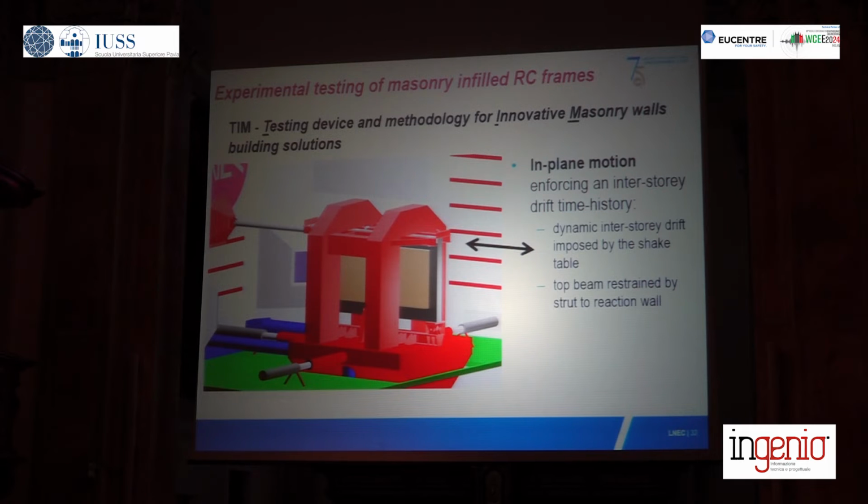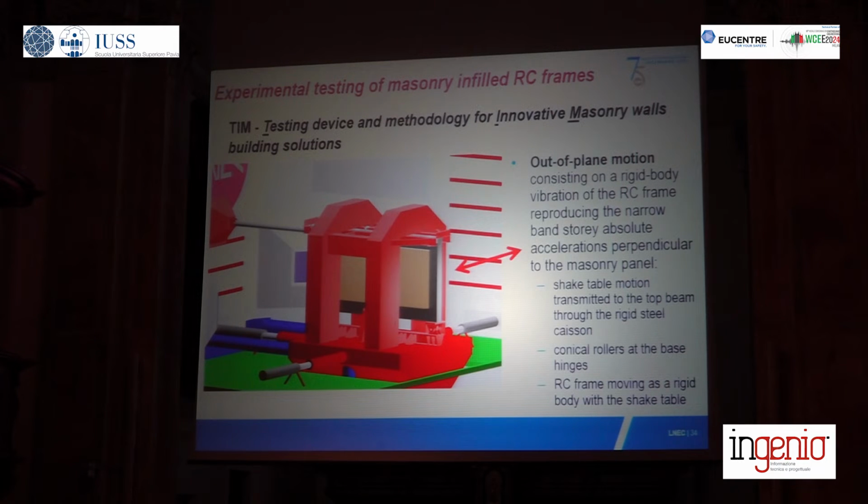Okay, so we impose the in-plane drift by having a fixed strut to the reaction wall and the motion of the shake table in the in-plane direction, and then we impose the out-of-plane motion, which consists of a rigid body vibration of the reinforced concrete frame, and then the relative vibration of the infill wall.